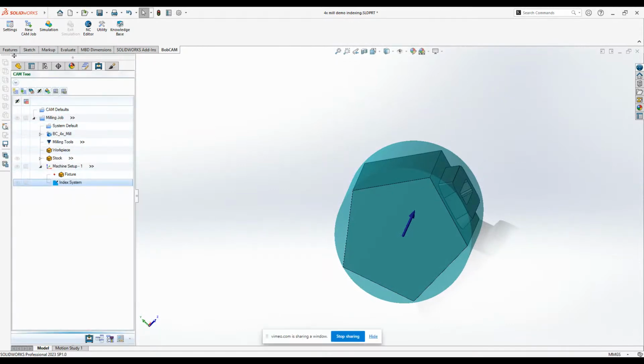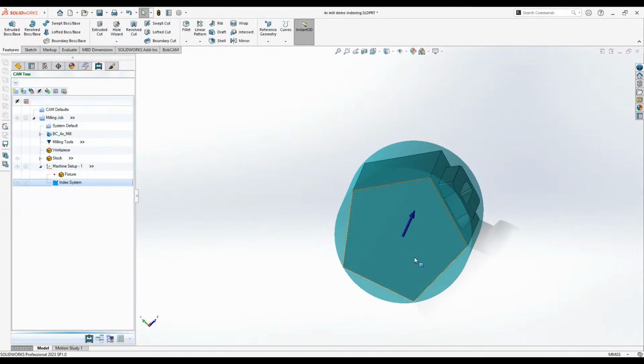So I remember with creating the features, I do have it in a SolidWorks part file I could go into, but I think we should maybe explain it a little more here of how to create that reference geometry in SolidWorks. So we go to reference geometry. That's under features in SolidWorks. Go to reference geometry and go to plane.